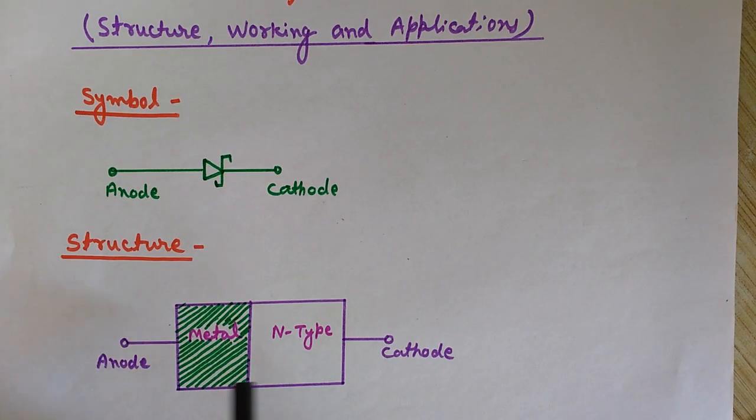So there is no problem of charge storage at the junction. Therefore, the diode can be switched at very high frequencies. That's the reason the reverse recovery time issues or the charge storage issues in the junction are not present in the Schottky diode. So friends, did you get the concept?